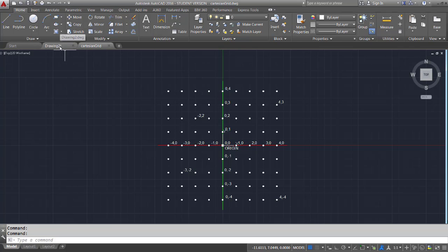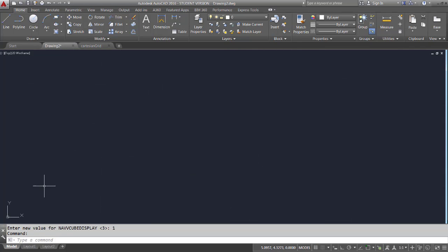So let's go back to our drawing screen, and we see that little symbol, that XY, is down here in the lower left-hand corner, and because we are in that upper right-hand quadrant, that in fact marks the origin for us, the 0, 0. And one way I can demonstrate that is by starting with the line command.